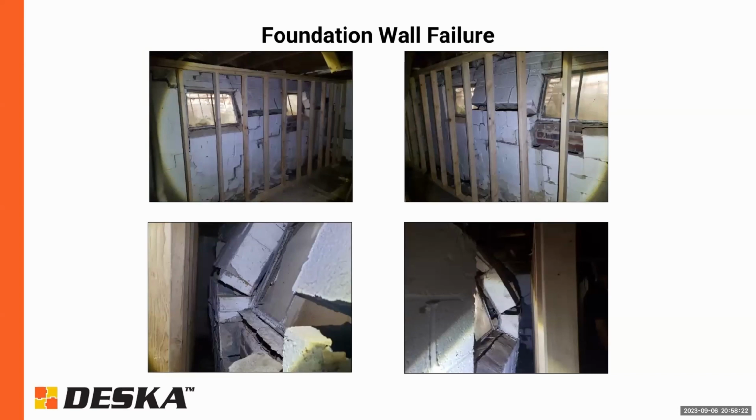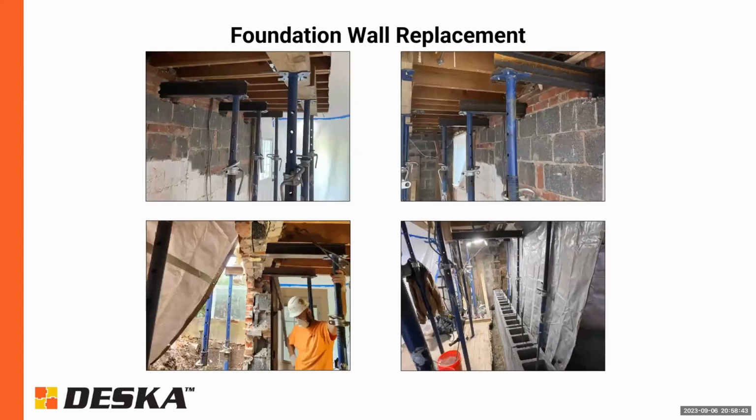Here's another example of a wall failure. This wall has really just bowed in too far, and required replacement. And in this case, the vertical bracing only there is really not doing the wall any favors at the moment. And it has quite a brick facade above this as well that's just very heavy. And so here's an example of a wall replacement, where you have a block wall along with a brick facade above it. And where that becomes very precarious is in the temporary bracing.